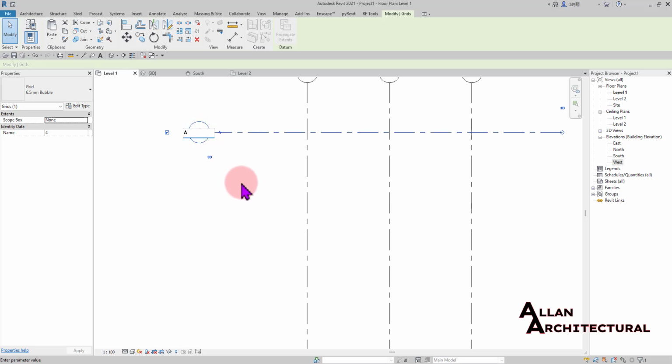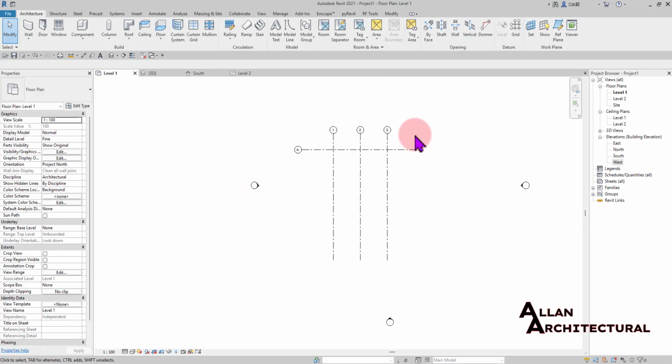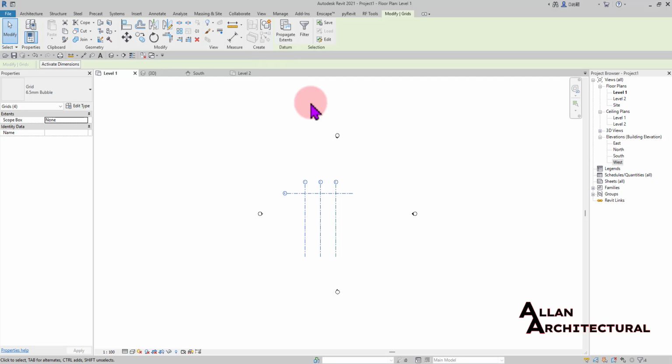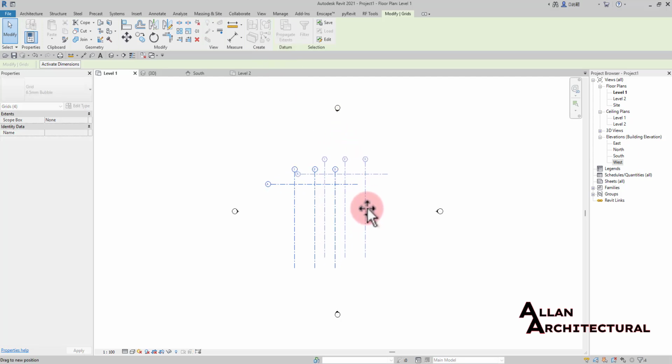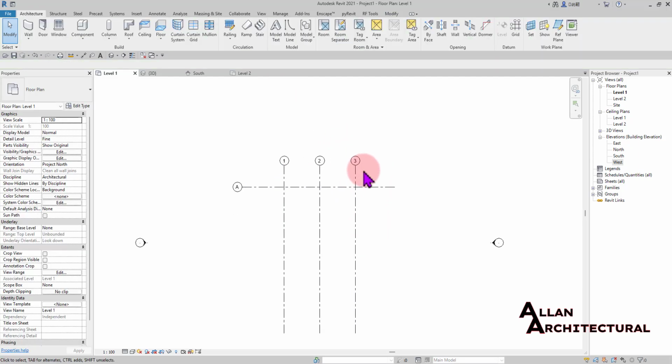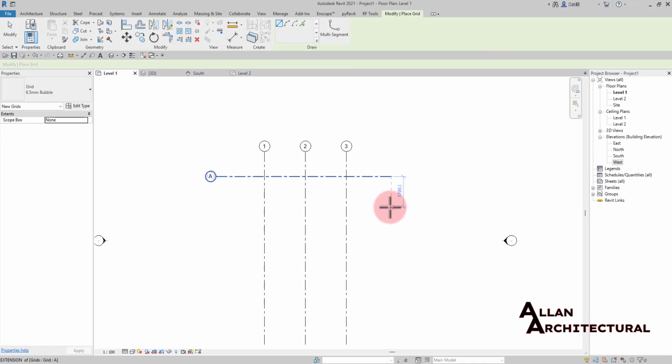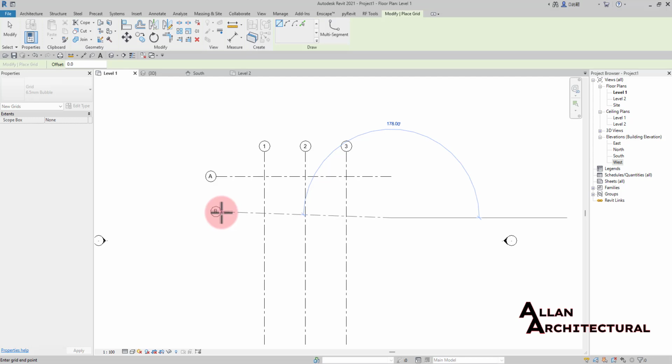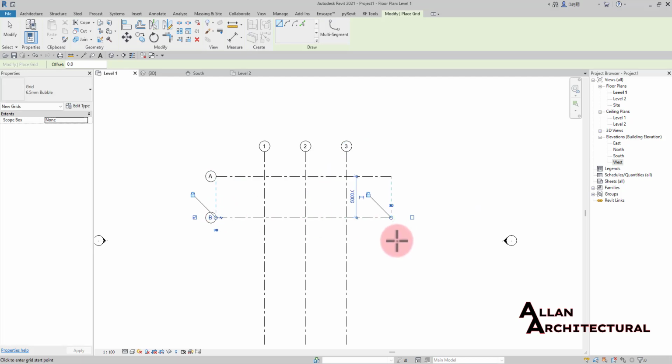All right, so when you change this to A, Revit is also automatically going to recognize that you are using alphabetical order. So every grid you are going to create is going to follow that pattern. So you're going to use 5,005 meters. So create that. Now you notice we've changed that to B, right? If I change this to a number, it's going to continue from that number. So you need to pay attention to that. I've spoken severally about that in my working drawing series.